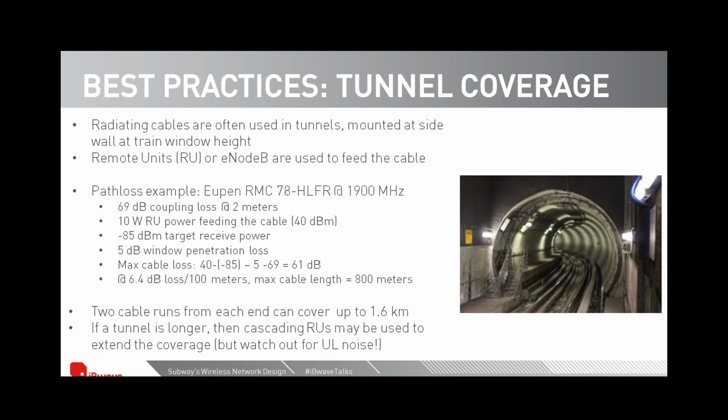And with that in mind, we have 6.4 dB loss per 100 meters, so maximum cable length is 800 meters. So if I have one cable coming from one end and the other cable coming from the other end, and they meet in the middle, I can cover up to 1.6 kilometers.